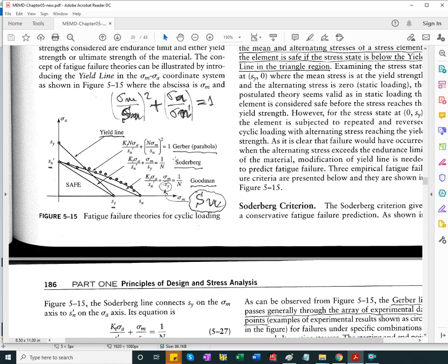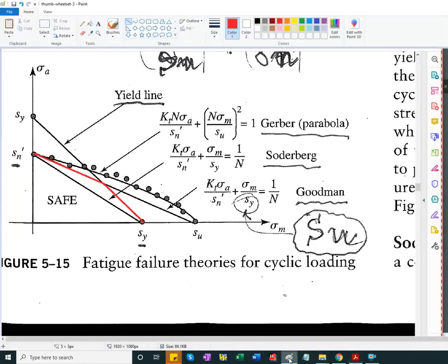So let me go back to this and explain. I'm drawing one, sorry for this. I'm drawing with blue color, dark blue. Firstly, this would be a load point. So you calculate the mean stress, you calculate the alternating stress for your problem. The load line, you get it if you connect the load point with the origin, no load.